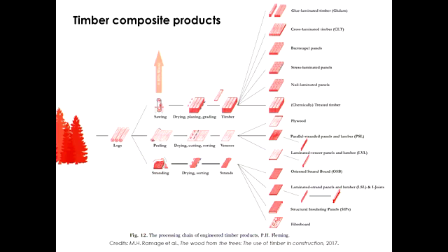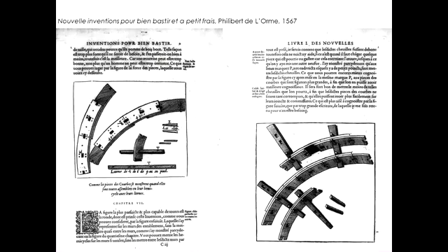So from timber boards, you, for instance, would get the glue laminated timber, or glulam, CLT. All right? You probably have seen glulam, or you've heard that before. From the veneer, you get the plywood, and you also get the LVL, which is the laminated veneer lumber. And from the strands, you get the oriented strand board, and a few other products. You'll see why I'm mentioning this in a moment.